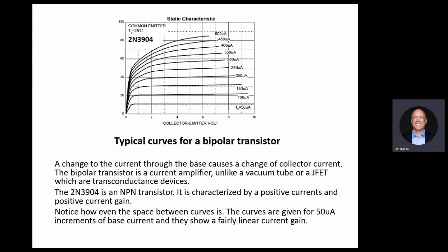I won't go into how to design with bipolar or how to design with any of them. I'm just mentioning the characteristics of the device. So you could, and people did, design good phono stages with bipolar transistors because they're extremely linear. However, they consume current, so they load the previous circuit.